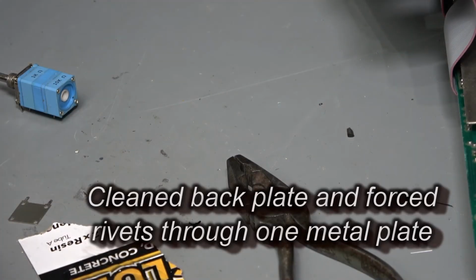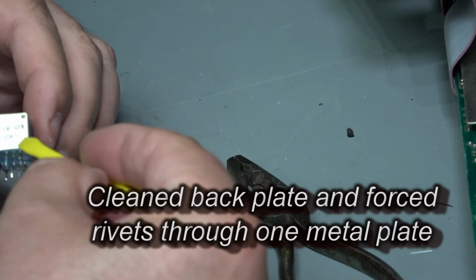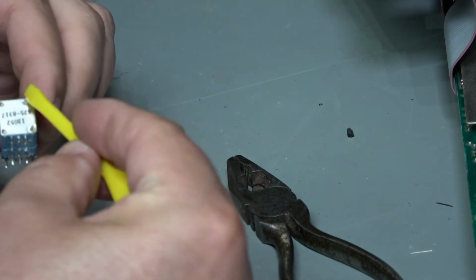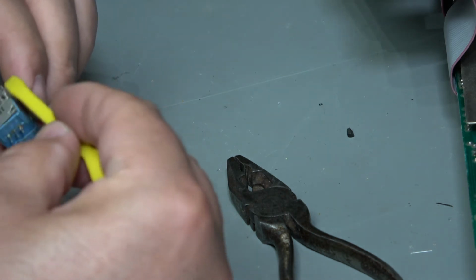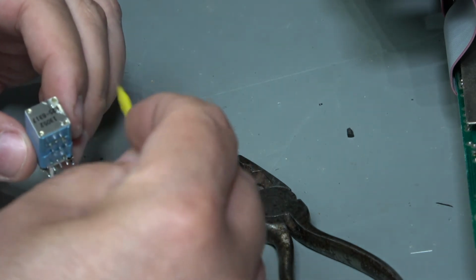Just want to make sure that this is absolutely clean before I attempt to. So I've forced the little things through the back, and what I'm doing now is I'm trying to make sure that I fill the hole. Got to get epoxy resin into that hole. It's not good enough just to wipe it on the back. This is a 5-minute set epoxy resin, so I have to work quite quick.